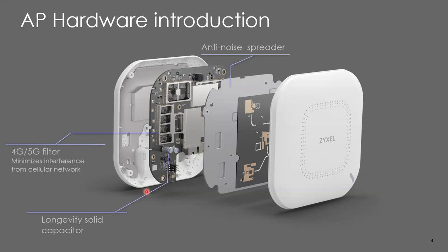It can cause the switches inside the microchips themselves to get locked in position. Heat fatigue can also cause solder joints to fail over time. So we have a lot of venting in our enclosures. You will also notice on most of our APs, we have a large metal heat sink behind the PCBA, designed to draw heat off the PCBA and vent it out of those holes.